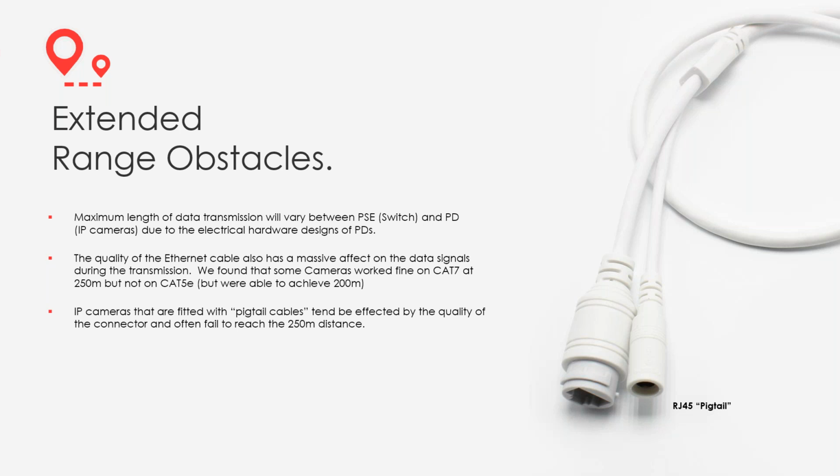So the obstacles that we have with extended range PoE is that not all devices actually support it up to standard. And also, since cable length and cable attenuation becomes very important, if there are low quality cables or if there are damaged cables in any way, the range might suffer.